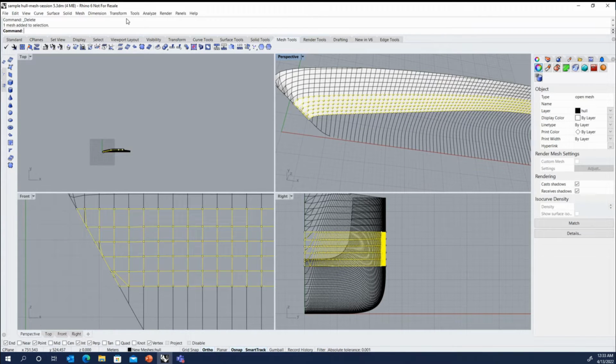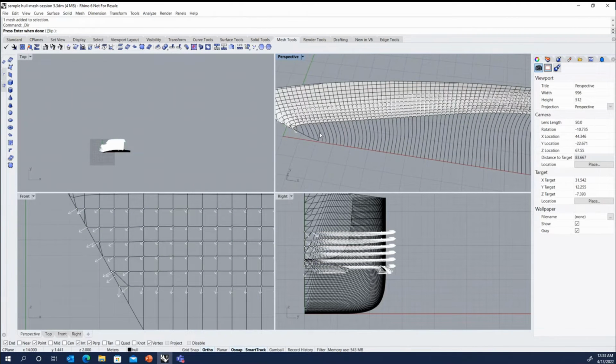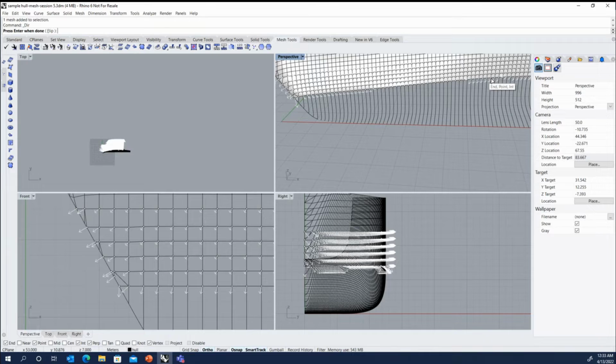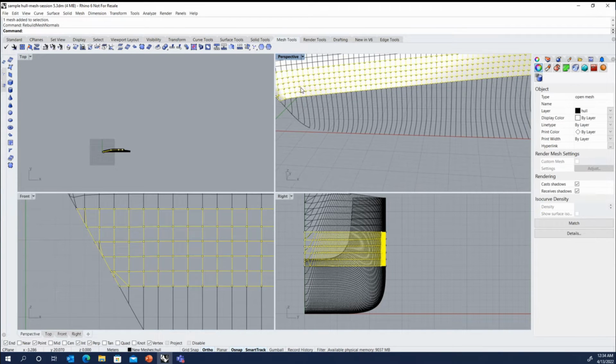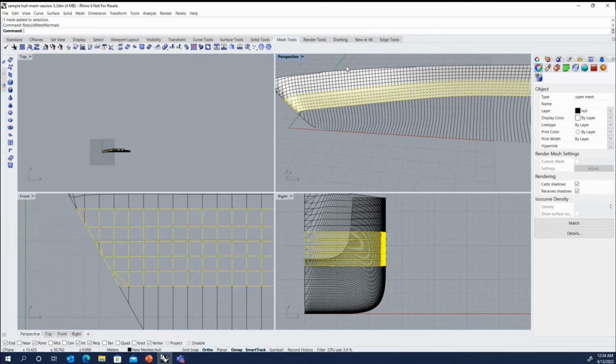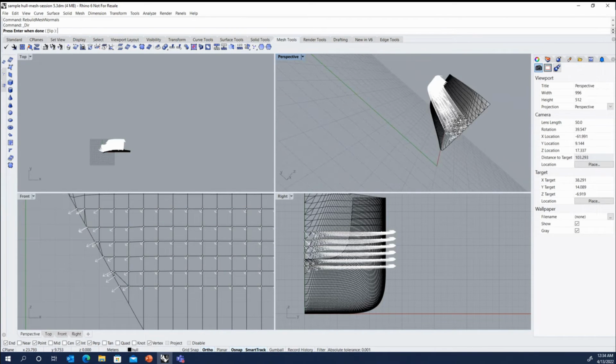Now our normals might be a little odd. Check the directions. They actually don't look bad, but when you delete something, you can see where that odd right angle was in the mesh, it sort of distorted our normals at the corner there. But now that we've deleted that flat edge to the mesh, we can rebuild mesh normals, and you can see the shading updated. And now if we were to check direction, everything is good.